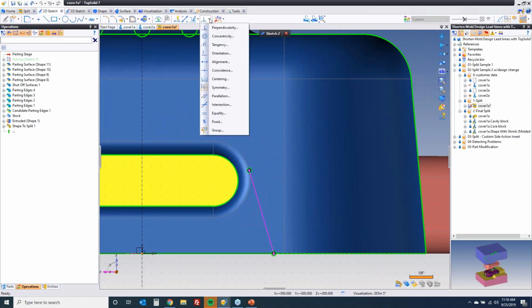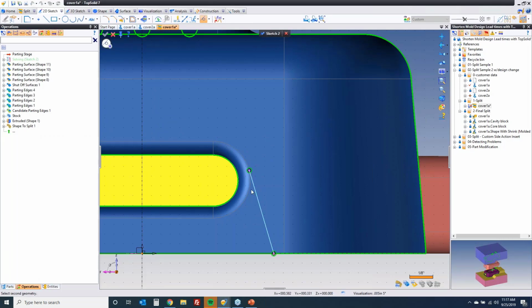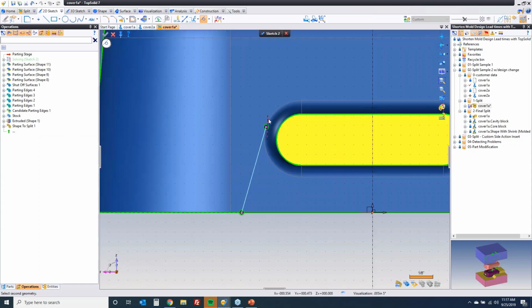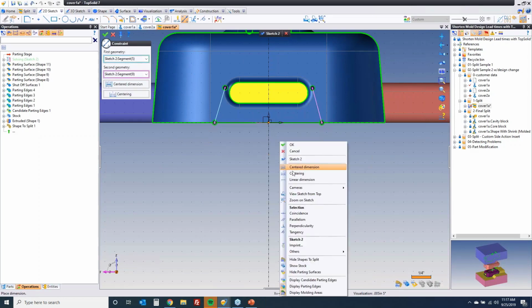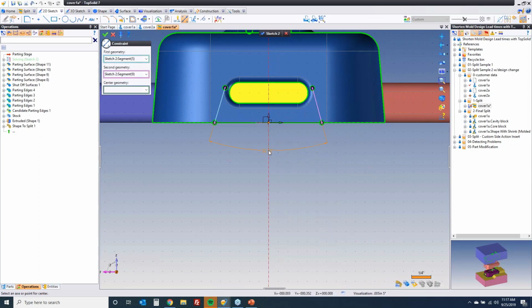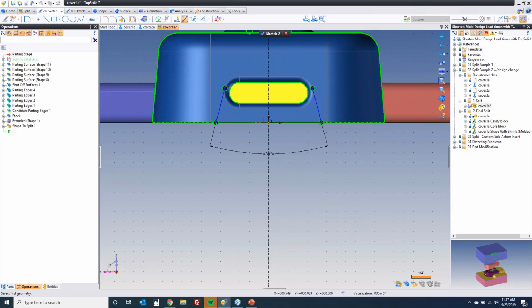And now we're going to add a couple of constraints. So here I want to be, let's say tangent between this and this at that point. Tangent between this and this at that point. I'm also going to add a quick dimension, and we're going to talk about what we just did there. I'm going to go here, say this is 30 degrees, 15 per side. Now, I made this tangent to that, right? But here's what's cool.